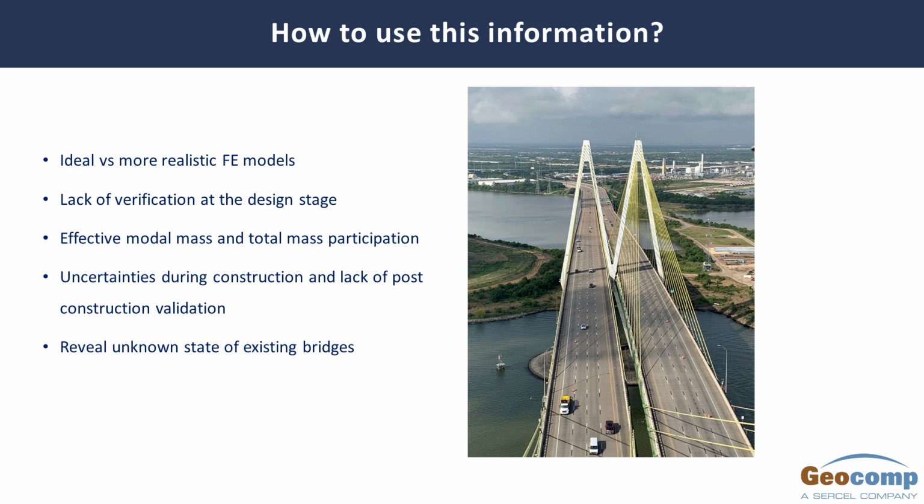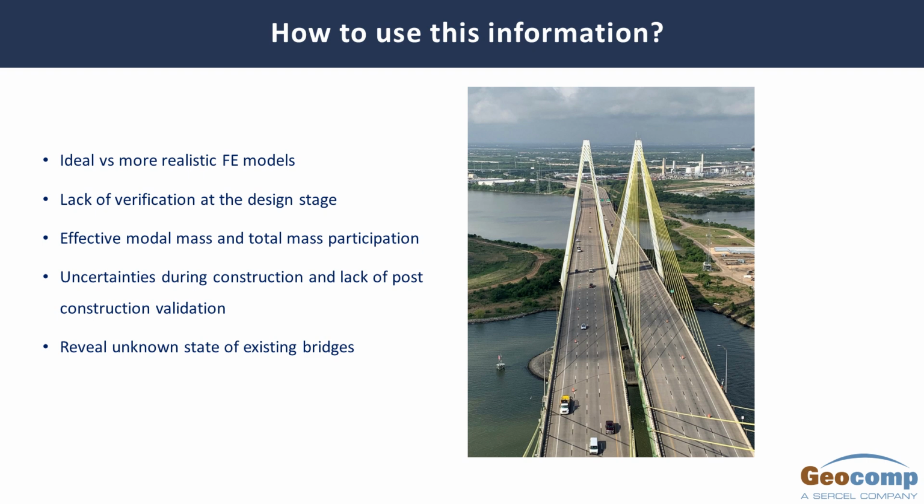Again, for finite element modeling, if you are doing dynamic analyses, the way you look at your modal mass, where it is concentrated, and how each mode has more modal mass participation can be done through modal analysis. Also, we all know that during the construction phase, because of some uncertainties or some things that go sideways, the original design may not really be satisfied.